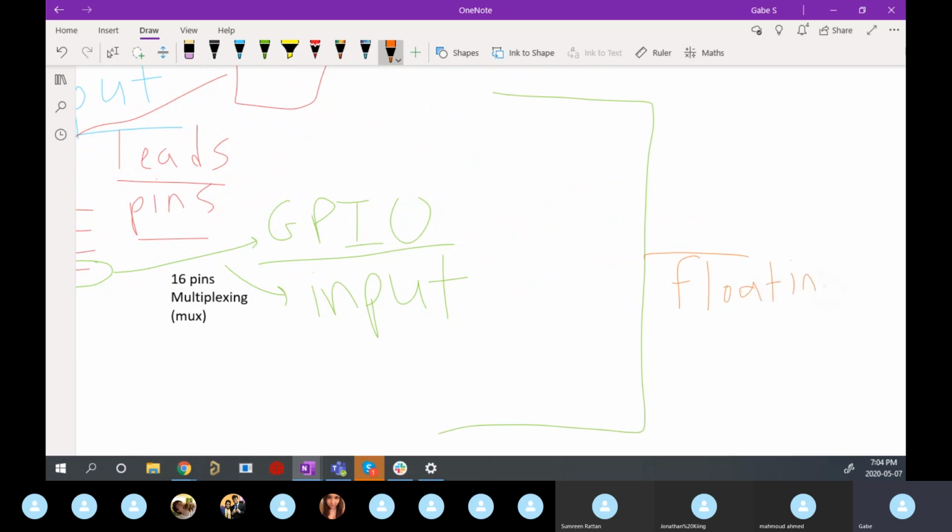This is often what happens when you don't have anyone to talk to. You're kind of floating, lonely, you're not sure if you should be a 2.3, you're not sure if you should be a 0, which I'm sure you guys have felt before. You're kind of in nowhere land. So what the pull-up and pull-down resistor allow you to do is to get rid of that undefined state.